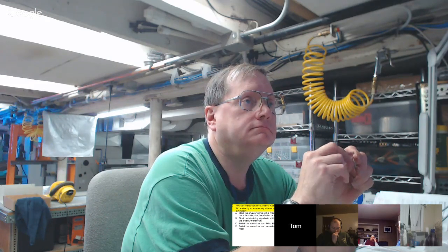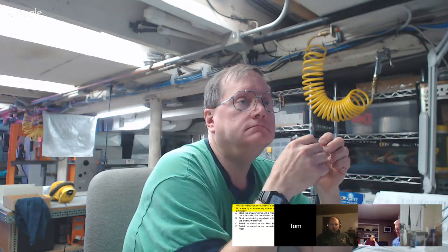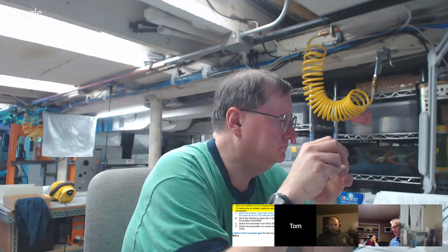How can overload of a non-amateur radio or TV receiver by an amateur signal be reduced or eliminated? And we're talking about an overload here. The simple answer to this is you want to block the amateur signal with a filter at the antenna input of the affected receiver. I had mentioned earlier a high-pass filter would allow only the TV station signals to come in and reject the signals from the lower frequencies that are on HF or the amateur bands.